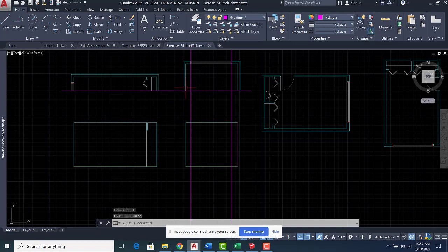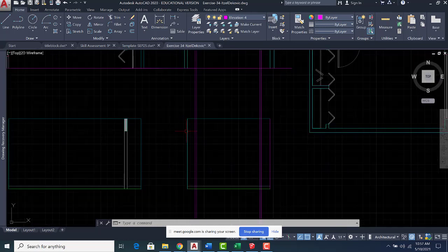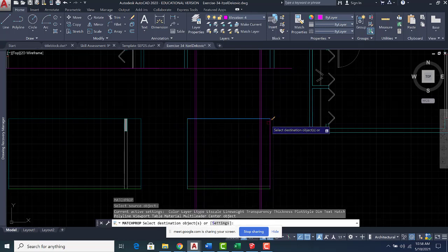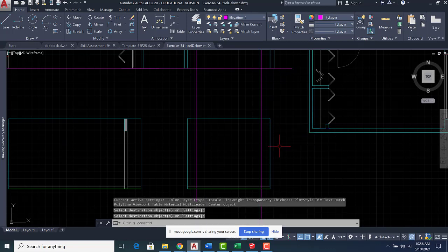You don't even need to draw it. I drew it to make sure it's in the right place. So maybe you can do the same thing. Draw it. If you see it's really on top of the other one, just delete it. Then I use MA, match. And these two, with the same thickness, I match them together.